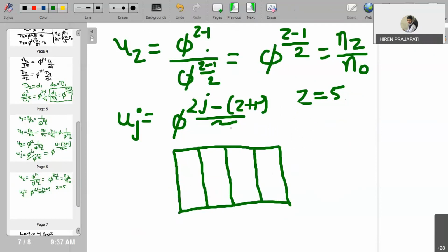So this is my input shaft, which is running at constant RPM, N0, and on the output shaft I am getting 5 different RPMs. Let me call this line N1, this N2, this N3, this N4, and this N5. What I have done here is just change the orientation. In the previous gearbox types, such as the all-gear type or the sliding cluster type, we drew the speed lines as horizontal and the shafts as vertical.